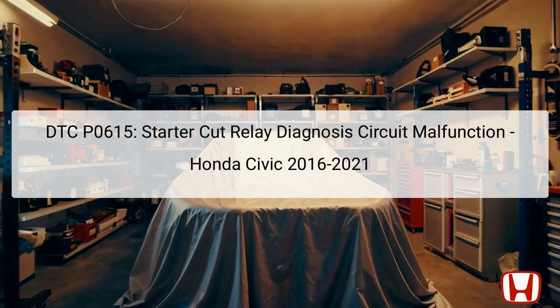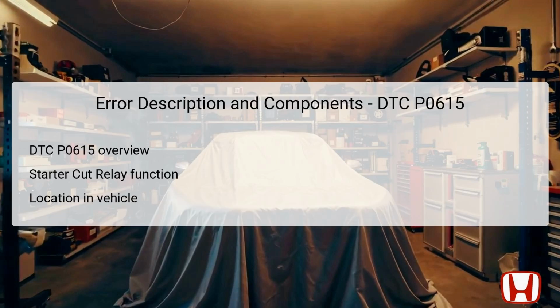DTC P0615 pertains to a malfunction detected within the starter cut relay diagnosis circuit, specifically highlighting a communication issue between the relay and the powertrain control module, PCM. The starter cut relay is integral to safely starting the engine by preventing unintended starts under certain conditions. It ensures that only when everything is confirmed as operational can the engine turn over.